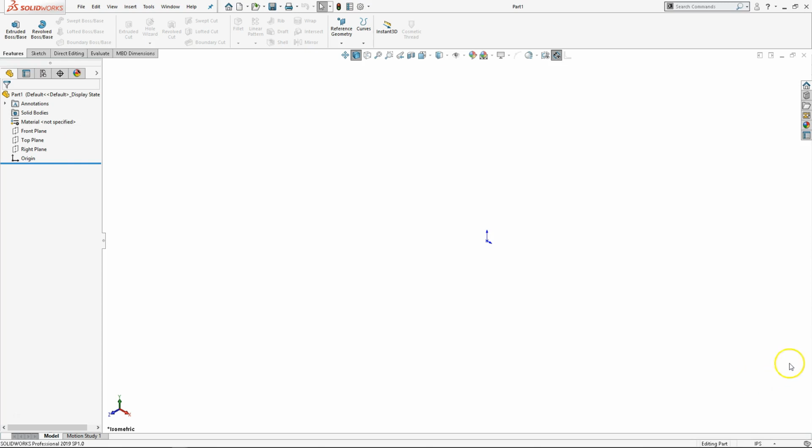Identify them out of the, let's see, that's going to be the little eyeball, and be careful of the little eyeball because if you click on that, it's going to hide all, and the little down arrow is going to give you access to those selections. So the little green dots that may be taking over your screen as you apply more relations are the add relations. If I click on that and then I go into a sketch, I'm going to see for every object its relations.